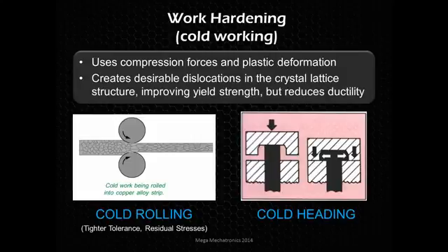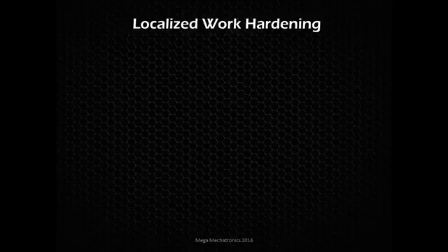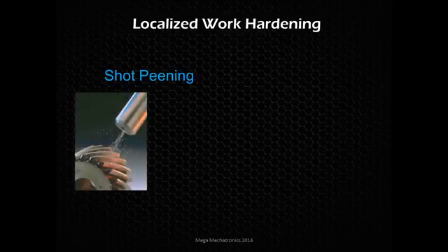In more localized work hardening examples, shot peening. So shot peening is totally different than shot blasting or sandblasting, because we're using very tight specification spheres of hardened material.